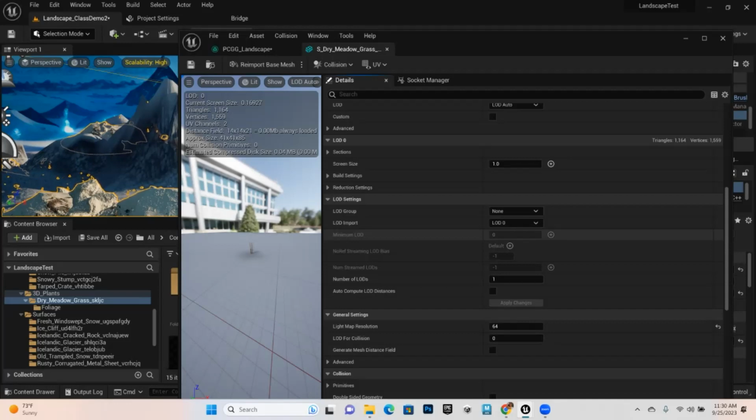And then it switches to LOD 1 or 3 or whatever is the next LOD that it has in the grass. And it's noticeable. Like as you're walking, you'll see your grass change. And it looks weird. It doesn't look good. And it does that for performance, but if you're not having a problem with performance, it would be good to come in here and just set your LOD